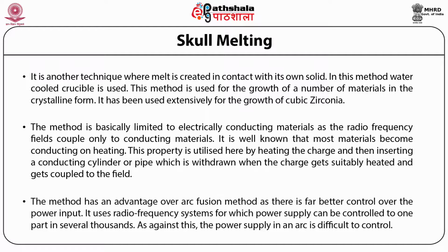The method has an advantage over arc fusion method, as there is far better control over the power input. It uses radio frequency systems for which power supply can be controlled to one part in several thousands. As against this, the power supply in an arc is difficult to control.